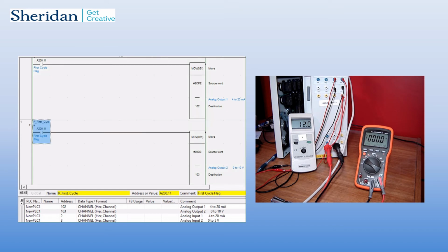And once I do that, what you'll see is that in analog input number 1, it's actually showing 6,021. Now I'm going to vary that analog input. As you can see, as I increase this, and I'll take it all the way up to 20, there we are, 20, which is full scale, what you see here is 12,006, 7. It's bouncing a little bit, but 12,000 is full scale.